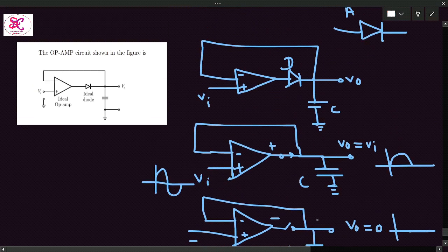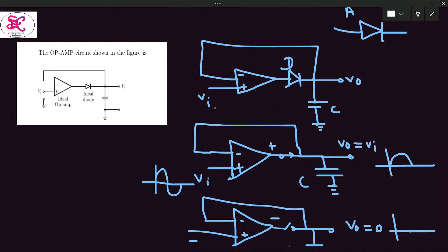And here we are considering the operational amplifier. So even if the input is a small value, the operational amplifier amplifies the input, which is applied to the input of the diode. So there is no voltage drop of 0.7 V in this case. Since the input is small, we are getting the amplified version of the input at the anode of the diode, and that's why there is no voltage drop of 0.7 V, and this type of circuit is called a precision half-wave rectifier. In this case, the circuit type is precision half-wave rectifier, and this is the solution of this problem.